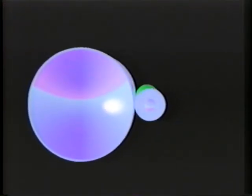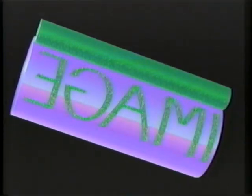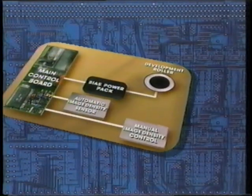During development, toner is attracted to the latent image because they have opposite charges, usually negative toner and positive latent image. Imagine what would happen if the development roller had a stronger positive charge than the latent image. The toner would have a stronger attraction to the roller than to the drum and wouldn't leave the magnetic brush. That's how the bias circuit works.